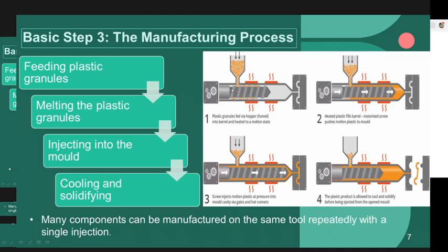The machine consists of a heated barrel with a reciprocating screw, which feeds the molten polymer into a temperature controlled split mold. The screw melts the polymer, and this also acts as a ram during the injection phase. The screw action also provides heating by virtue of shearing action on the polymer.